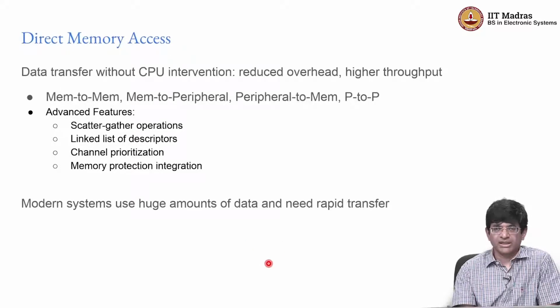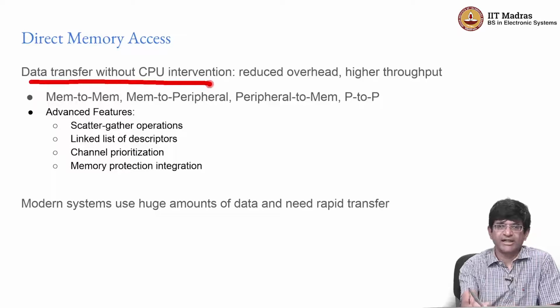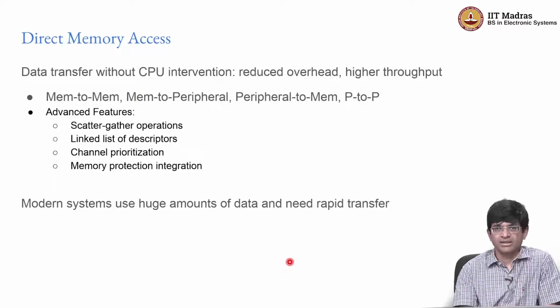Moving further along, the kinds of things that become useful in the context of hardware software communication, or the hardware abstraction, is direct memory access, where basically we want to be able to transfer data, right. The earlier example I gave was about how a UART is several orders of magnitude slower than a CPU, but so is memory, right. Especially, let's say that I want to copy a large chunk of data from one location to another.